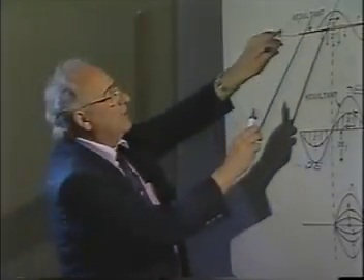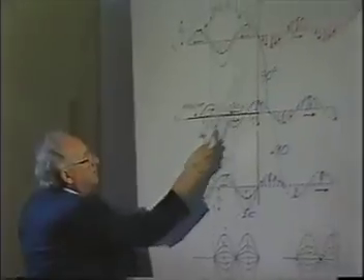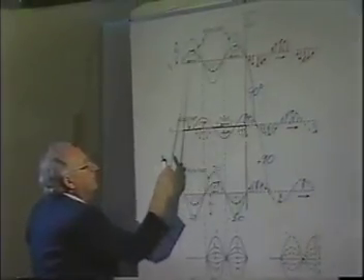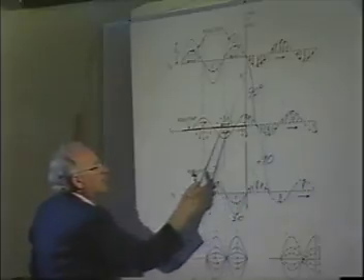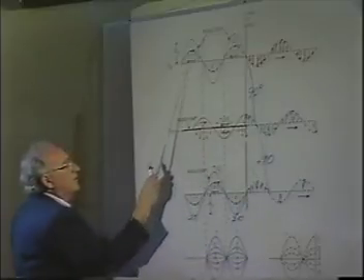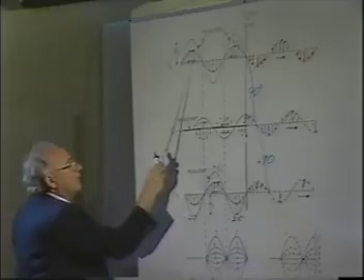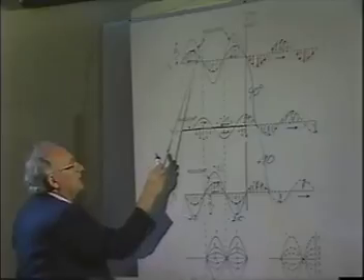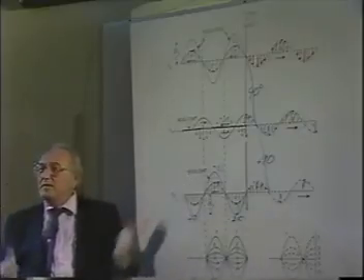If you could stop it here and look at this, this wave here is folded over here, this is folded over here, this is folded over here, because this, instead of traveling to the right this far, has traveled to the left this far. It's positive, meeting it with the positive wave going into the right. This is going to the right, maximum positive. This is going to the left, maximum positive. Adds up to 2e at that point.